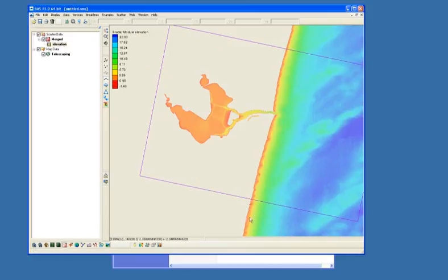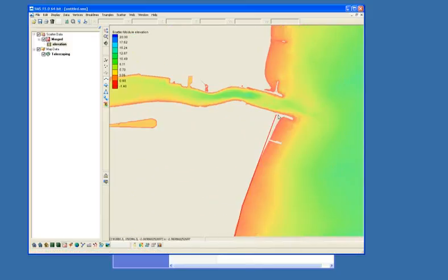So let's start this over again. I'll create an arc. Let me get rid of that one first. So I'll start creating an arc, and just click the points until the land is described. If you make a mistake and you get too far in, you can hit your backspace key and actually back up one point. And so you can just click this out.